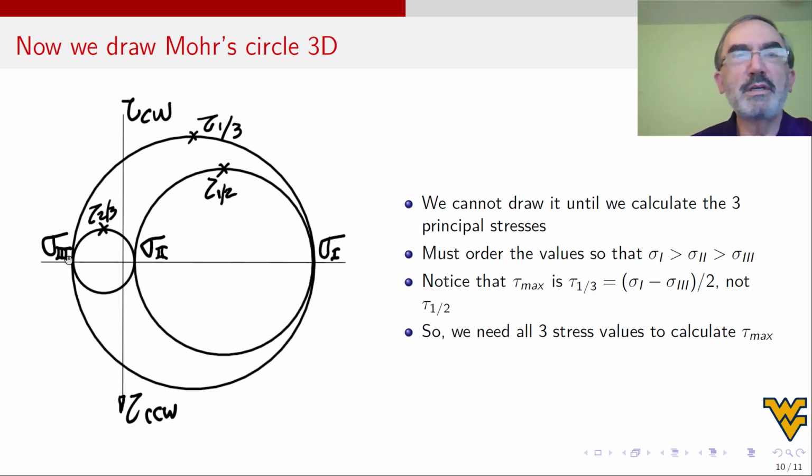So once you have this number and this number and this number, what do we know about Mohr circle? We know, because Mr. Mohr said that all the possible states of stress have to be on the circle. They cannot be inside, they cannot be outside. They have to be on the circle. So what circle? Well, between 1 and 2, like when we did Mohr circle 2D, there was only 1 and 2, right? So between 1 and 2, we can draw a circle.